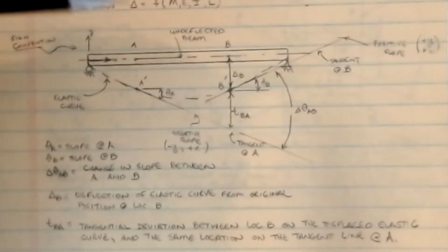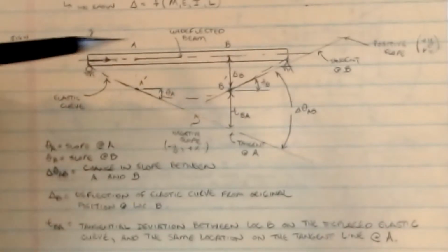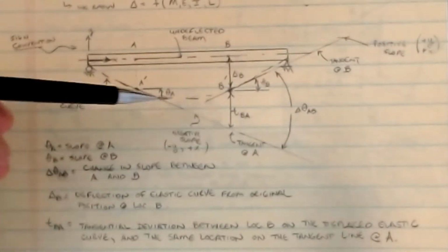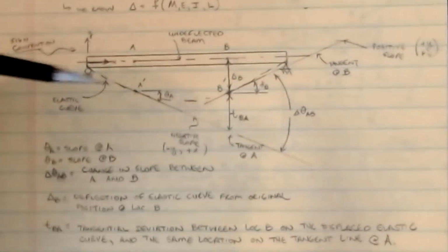These are all how we're going to do it. Everything is about choosing two points on the beam, and how you choose them is part of the strategy of the method. Then we look at drawing these tangent lines to those locations.